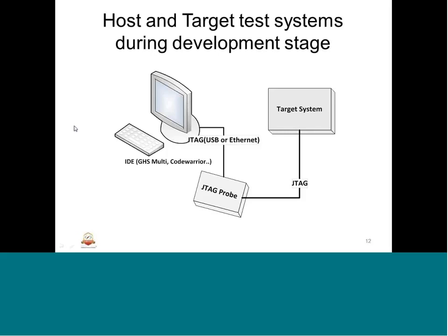I'll brief about this host and target system during the development stage. There is a laptop or desktop which will have an interface with the target system with the help of an IDE. The IDE generally uses probes which will probe the registers or the memory and all that hardware related information through a probe box called JTAG.